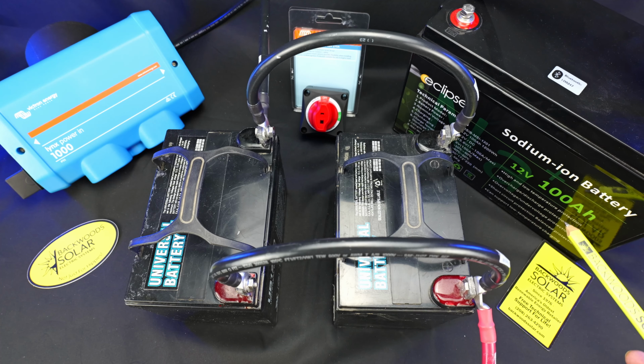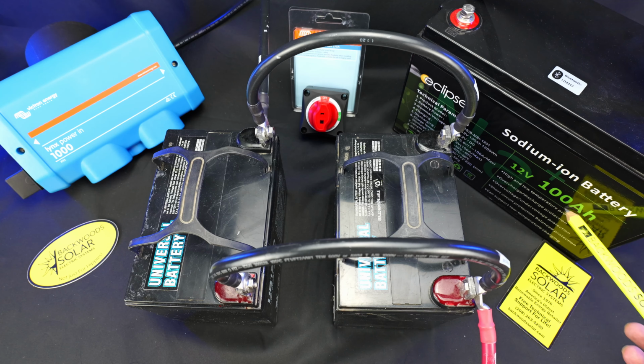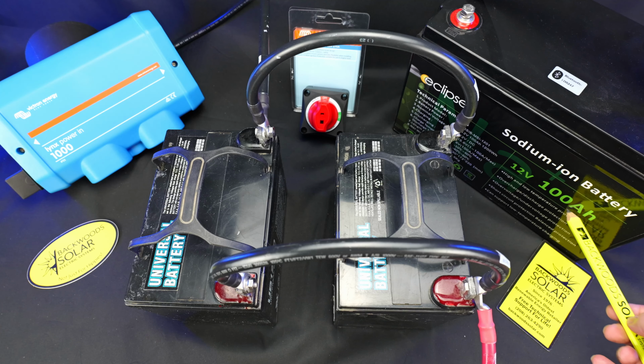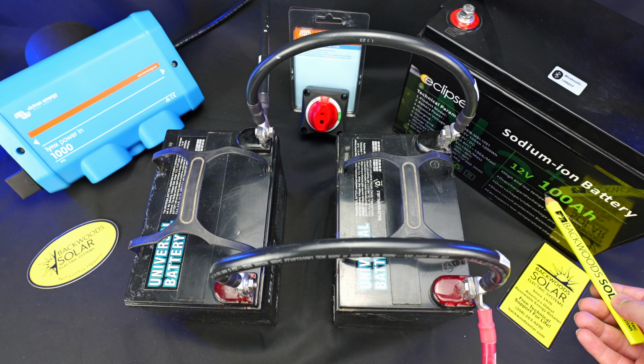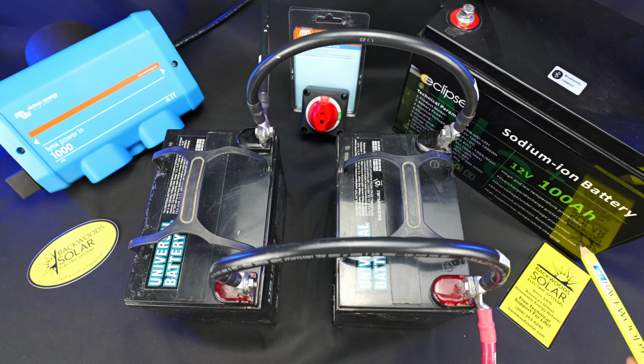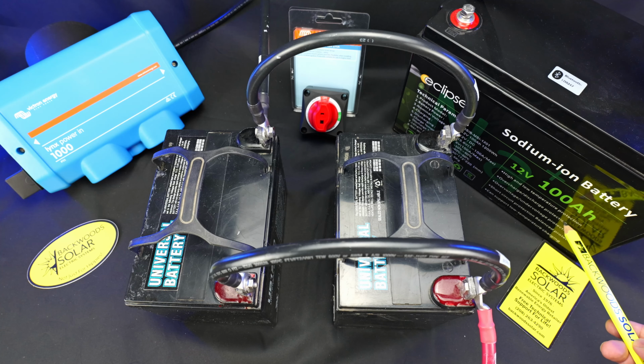The second figure most commonly found on batteries is a capacity or amp hour number. Amp hours is a rating of amps over time. So using this, taking out efficiencies, a 100 amp hour battery as an example could support a 100 amp load for an hour or a 1 amp load for 100 hours as an example.